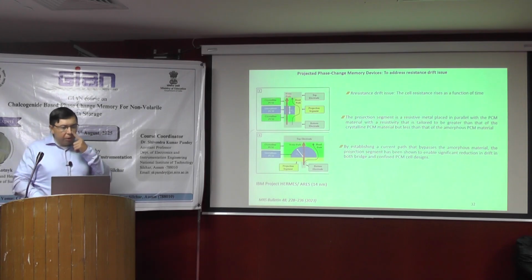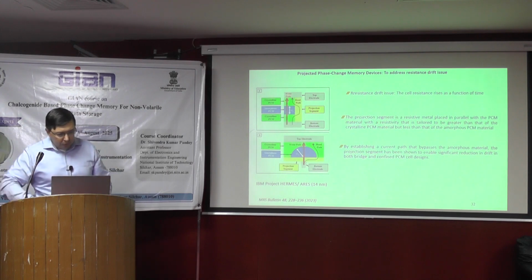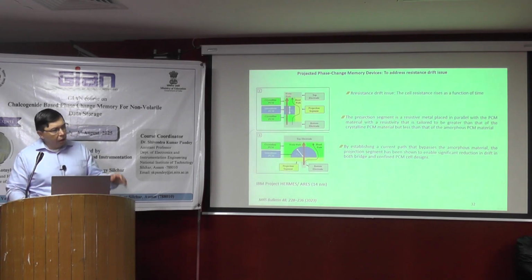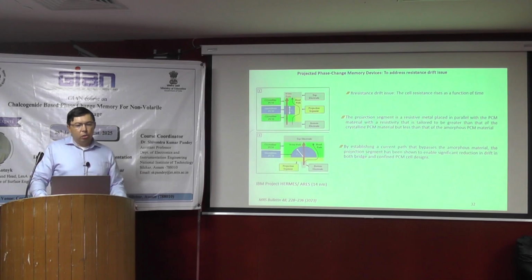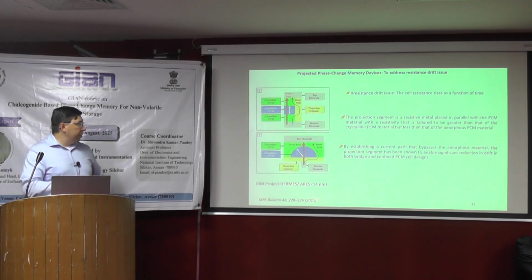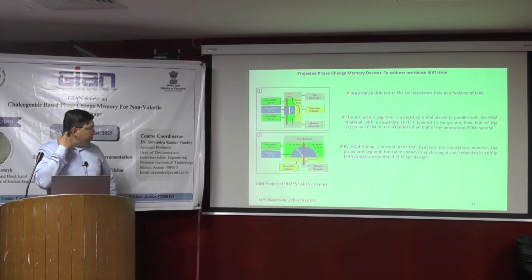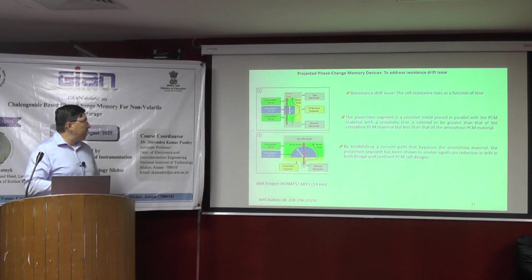There is also one concept. We have also many problems with PCMs. One is the resistance drift, that the material itself can change resistance over time. And to overcome this issue, recently in 2023, IBM proposed a so-called projection phase change memory device to reduce the drift of the GST cell, of a PCM cell.